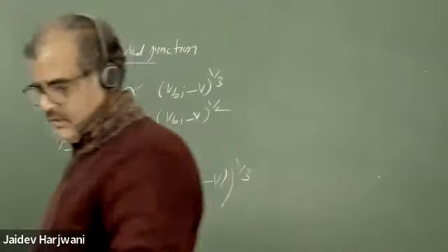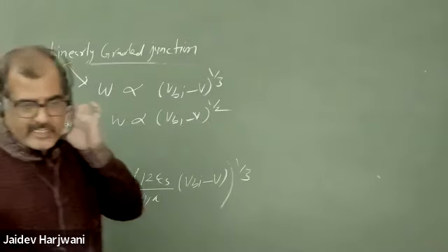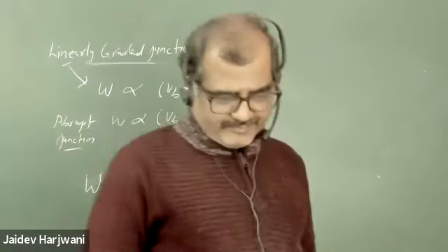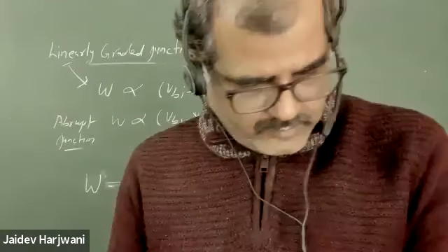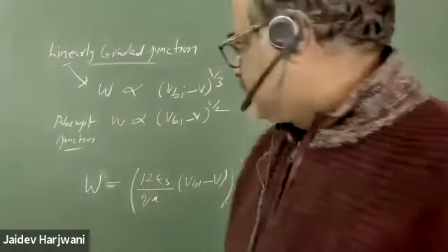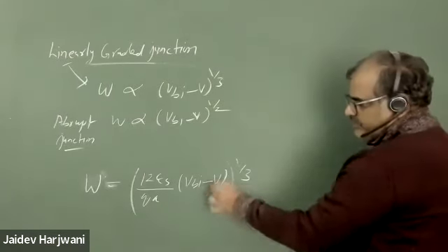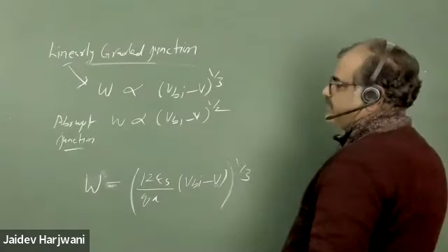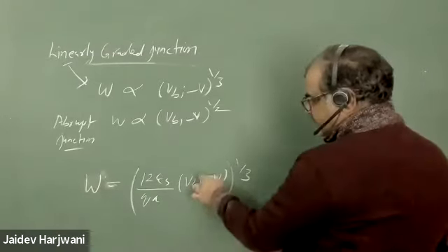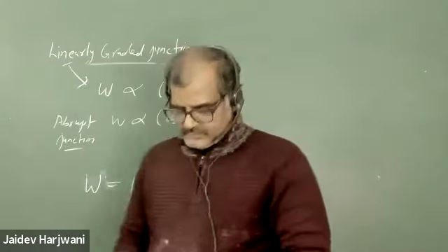Now, along the same line, if we continue, we can also calculate the junction capacitance. Sir, forward bias and reverse bias are as previous only, right? Yes, V is the same. If V is forward bias, you put it with positive sign; if reverse bias, you put it with reverse sign. So for reverse bias you can put plus V_R here.